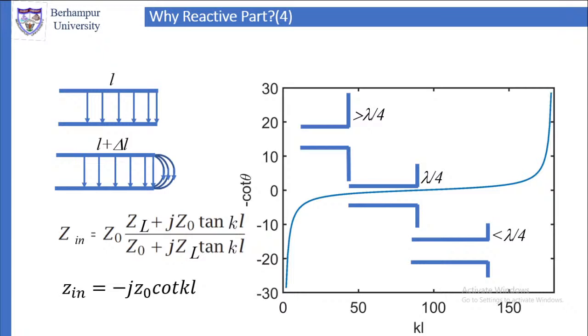So the resistive part plus inductive part has changed, so it will not be 73 ohms. All these things happen. The frequency goes down, the impedance is not purely resistive, the resistance is not 73. All this happens because of this elongation in length, the electrical length being more than lambda by 2. So what is the solution?